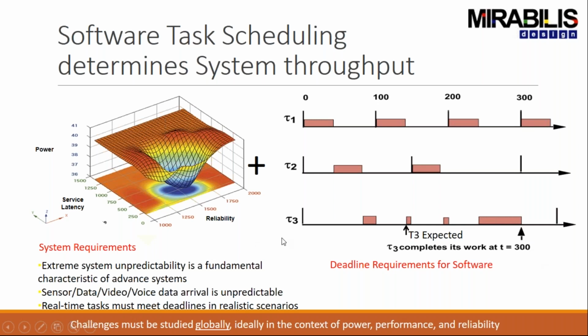So these are the task deadlines, which are really important when you deal with an RTOS system, a real time operating system, where we need the real time deadline. We need the task to be completed within that deadline, within its execution time. And all these things can be analyzed.